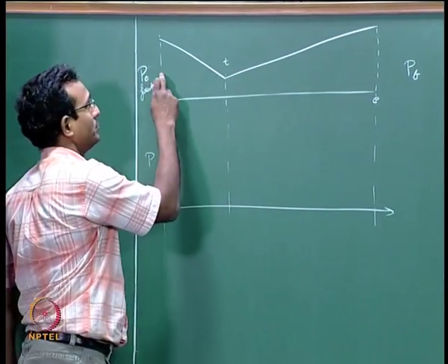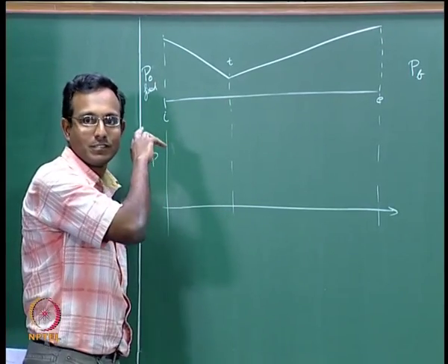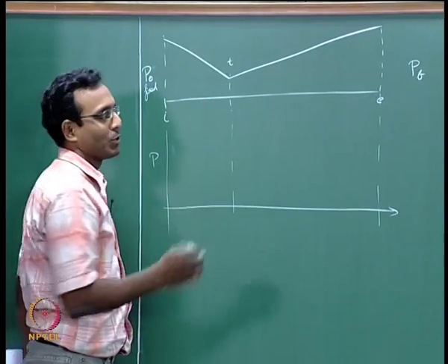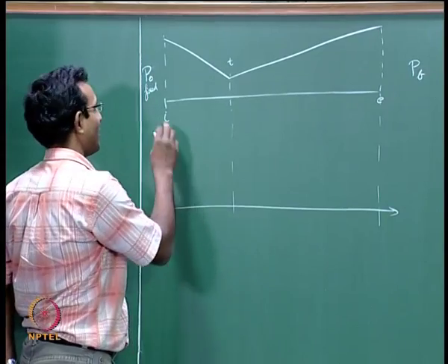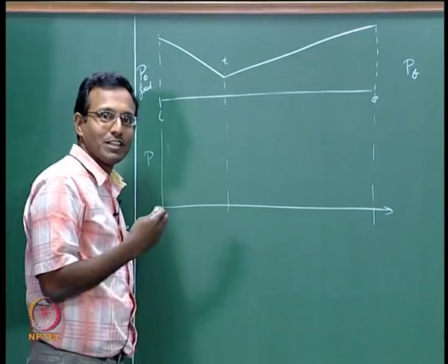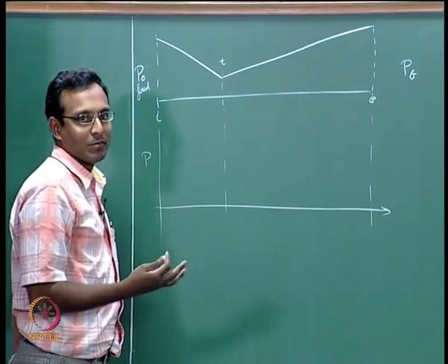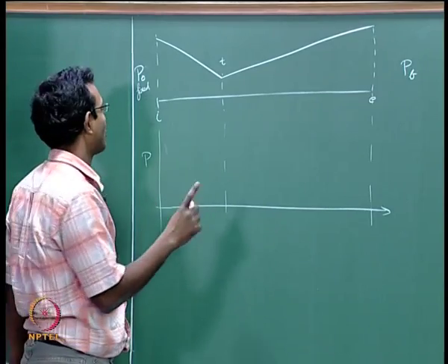Okay. And if I look at what happens to pressure as a function of distance, we know that from here to here the flow accelerates and P naught is maintained constant, at very low subsonic values. We can even think about it as Bernoulli's equation, and we can tell that when velocity increases, pressure decreases. Even for compressible flows, when Mach number increases, pressure decreases, for isentropic flows, and we are still using isentropic flow.